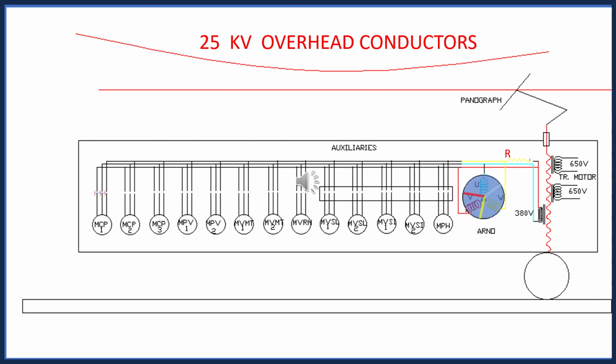According to the horsepower of the electric locomotive, it will take current from the OHE. You convert horsepower into kilowatt, then divide by 25 kV, and you can easily find the current taken by the main transformer. The traction motors' current rating also I will tell you with a chart, so that you can understand the amount of current for various locomotives.